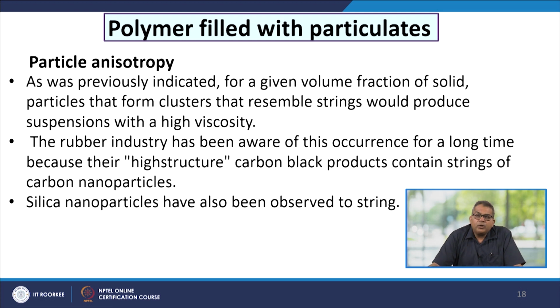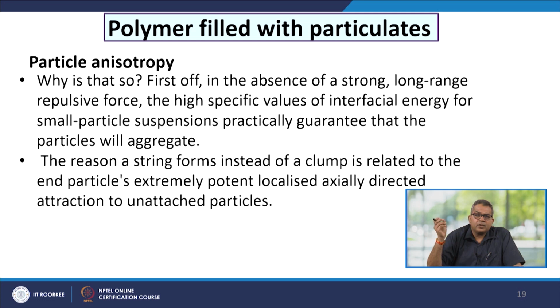Now, for a given volume fraction, solid particles that form clusters resembling strings would produce a suspension with a high viscosity. The rubber industry has been aware of this occurrence for a long time because their high structure carbon black products contain strings of carbon nanoparticles. Silica nanoparticles have also been observed to string.